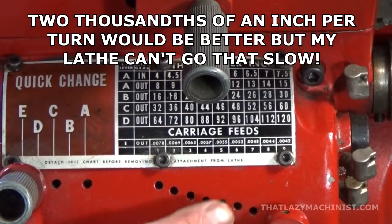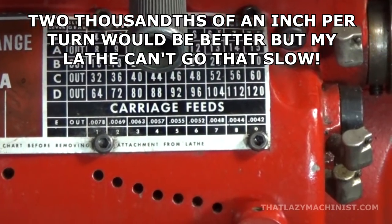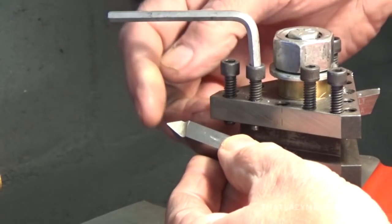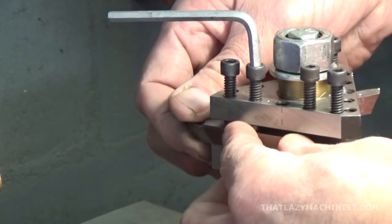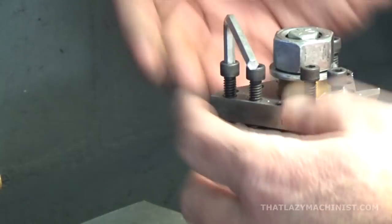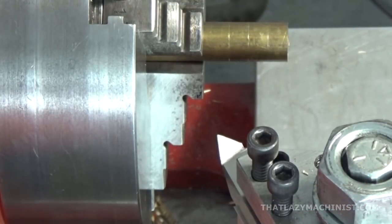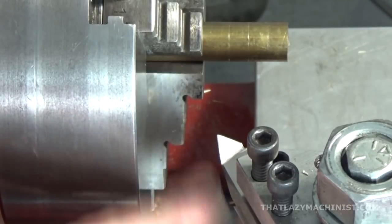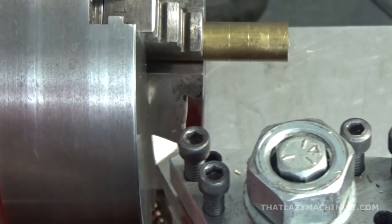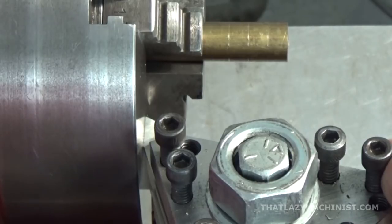I'm also going to want a slow feed, and on my machine here, about 4/1000ths of an inch is as slow as it goes. I'm going to mount the tool so that the cutting tip is exactly on the axis of rotation of the part, height-wise. Very important. And since with this technique, the cutting edge of the tool is going to form the shoulder of the part, I'm going to want that edge to be very perpendicular to the axis of rotation of the part.